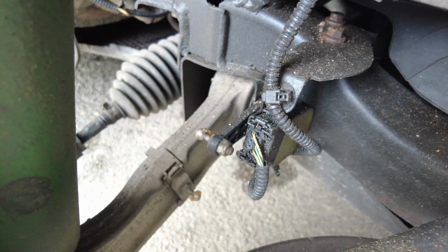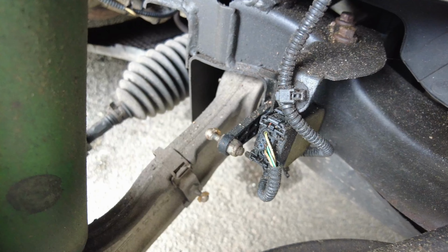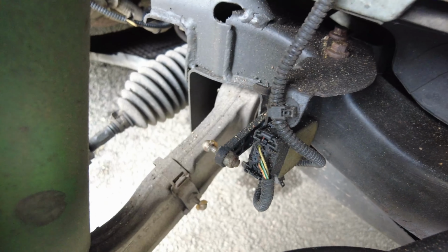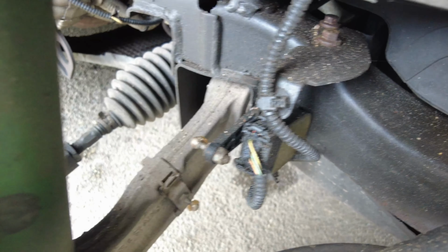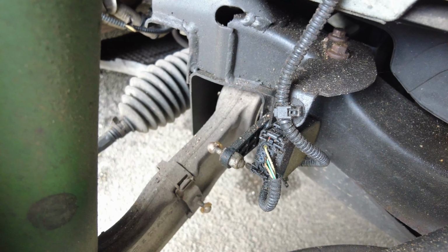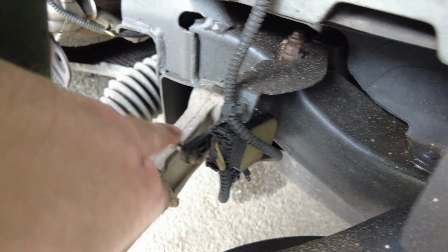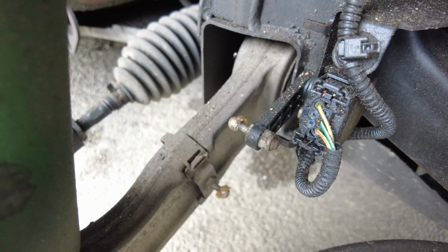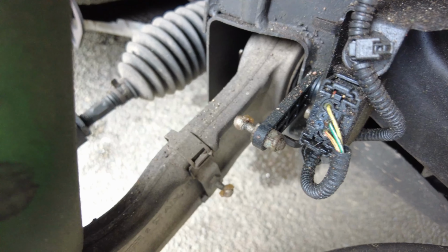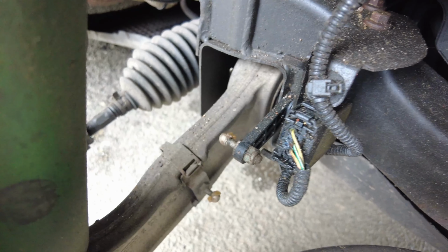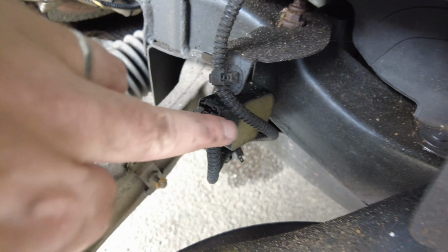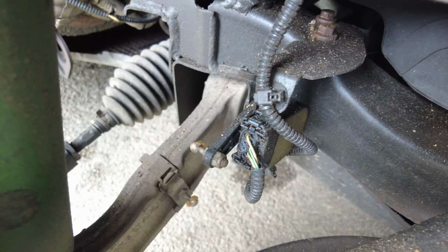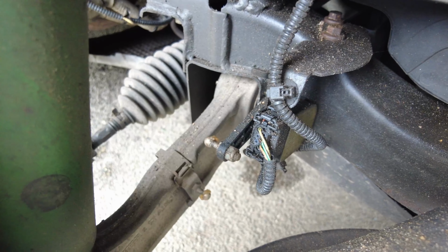So it means that regardless of what's going on with the suspension, this reading will never change. I think what I need to do is rescue the linkage arm from the donor item that I have, clean up these ball joints and see if I can attach these, so that we actually have a functioning front axle sensor that can take some readings from the suspension arm.